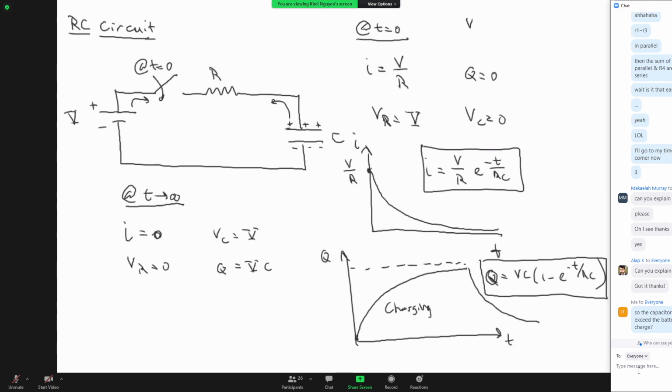The voltage is equal to current times resistance, from Ohm's law, plus the charge over capacitance. So if you think about it, I is dq/dt, so this is q prime R plus q times 1 over C is equal to some voltage. It's a constant.